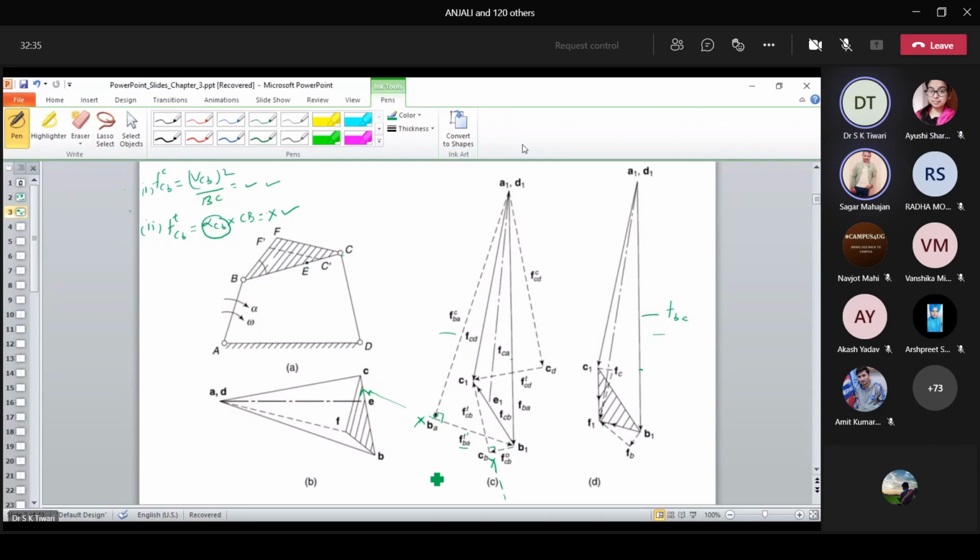Yes, sir. Just pay attention to what I am saying. Now again, as in the velocity diagram, point C can't be located with only one center of rotation. For locating the point C, D was also required. So the same case is going to be followed over here. For C, D is also the center of rotation. Therefore, I will first find FC, the centripetal or radial component of C with respect to D, and it will be velocity of C with respect to D square divided by CD. Velocity of C with respect to D, this vector, you can measure. It means you know the magnitude, you know the direction.